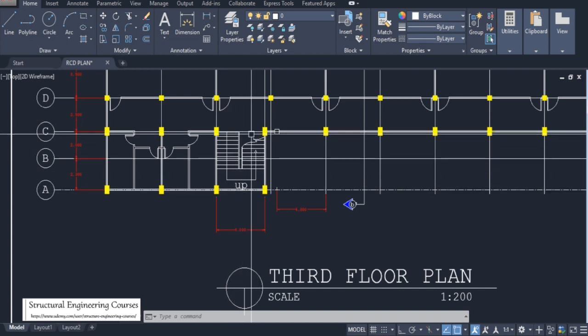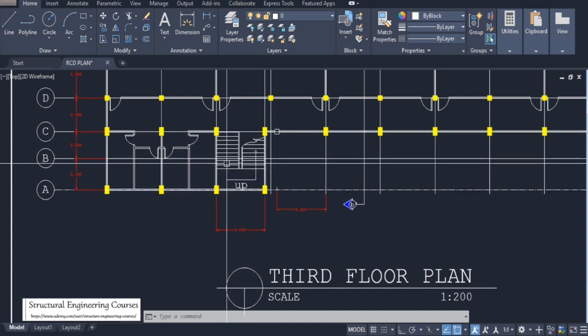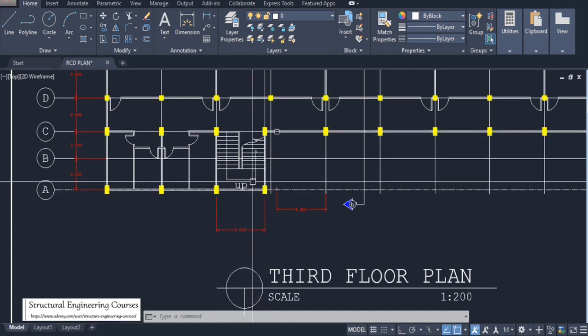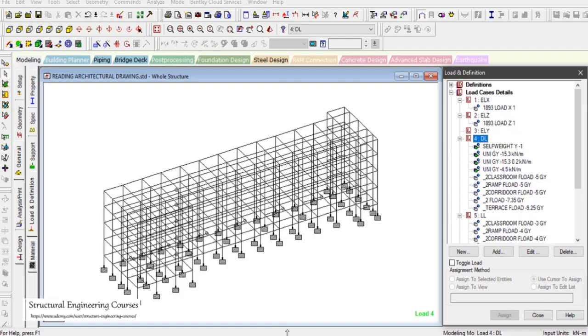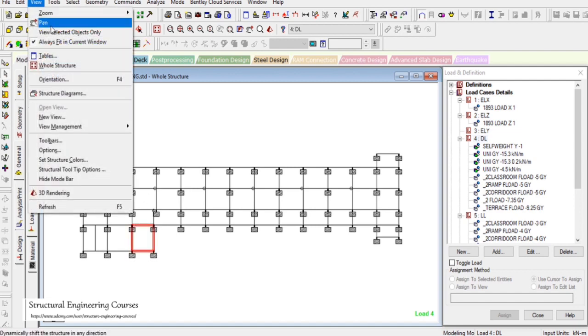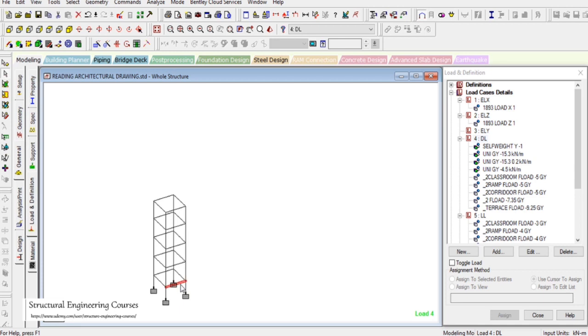So what modification we can do in this scenario is that we can delete the floor beam from this point to this point, as this area is a mid landing level only. So what we need to do here is select this particular area on which we do need to apply the staircase loading, and then we can model the mid landing beams here. And side by side we can now delete the floor beams here.